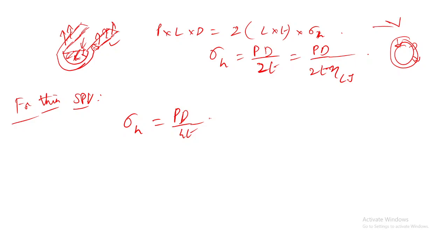In all these cases sigma 3 equals 0. Sigma 3 is nothing but the principal stress. Here, what will be the value of sigma 1, whether it will be hoop stress or longitudinal stress for thin cylindrical shell? For cylindrical shell, sigma 1 is always the greater value, so it should be hoop.